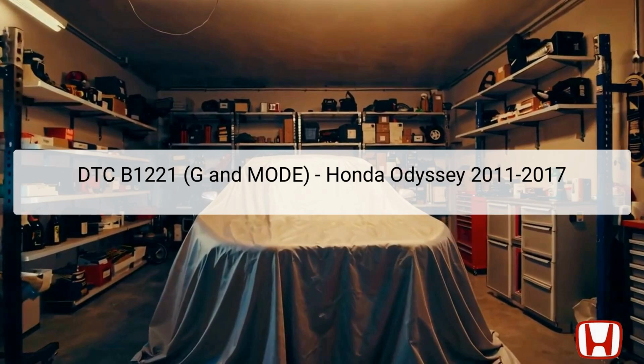The DTC B1221, also indicated as G in mode or code 7, signifies an open circuit in the rear mode control motor circuit of the Honda Odyssey. This error is specifically related to the rear air conditioning system mode control, affecting how different air modes are directed